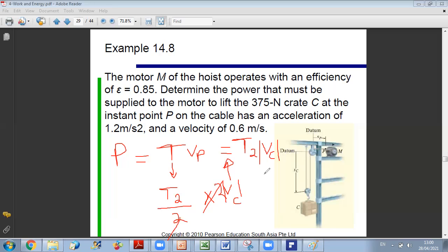So you can conclude here the concept of energy conservation. We have that the power is the same, but with a smaller force, this is the concept which will allow you to lift a much higher weight. Why? Because what you are doing through the system of pulleys is reducing the velocity.